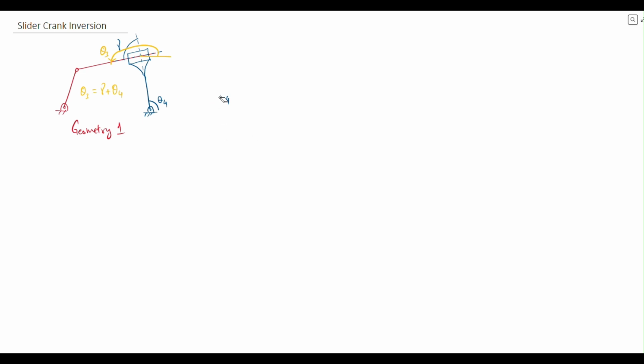We also saw in the case of velocity of slip, we revisited this mechanism, and we talked about in the analytical method how if we describe the loop closure as a e to the j theta 2, this is second, this is third, and this is fourth link, this is the first link. We can write the loop closure as this.